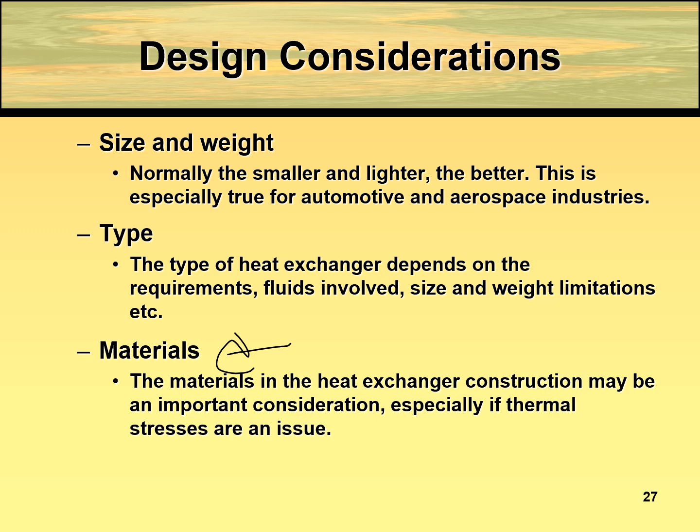You can refer to the compactness ratio. You just Google it, okay, compactness ratio, which is the volume divided by the area. And then finally, the material type that is going to be used for the heat exchanger. It depends on the type of fluid, and as well the type of material for the heat exchanger itself, the tubing, the shell, and everything. So that selection of the material will determine the size, the budget, the cost, and the overall perspective for the heat exchanger.